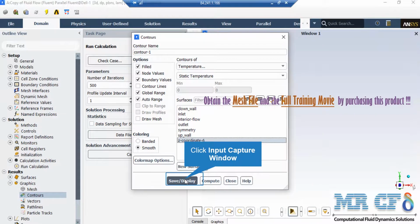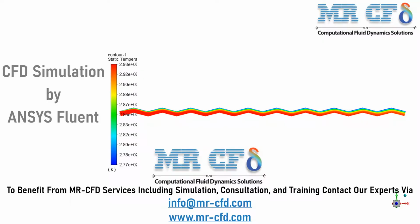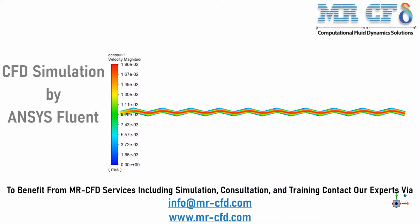For example, in this slide, we have selected the temperature variable, and then under the surfaces section, we click on define isosurface, which would be the z coordinate. After that, we click on the Save or Display button so that the software will show us the contour. Now in this slide you can see the temperature contour for this range of velocity and Reynolds number, which you can compare with the paper's result. In this slide you can see the velocity contour, which you can compare with the paper's result.